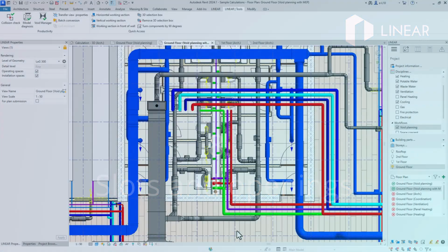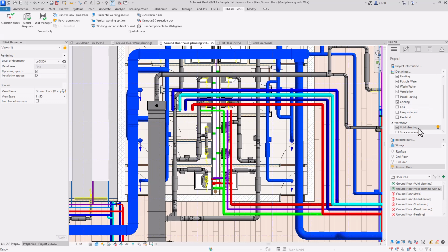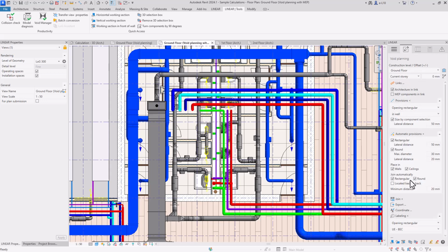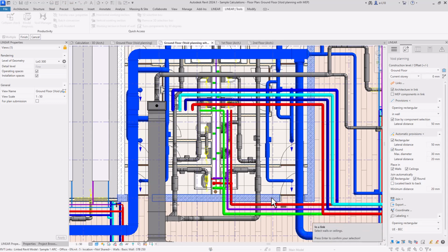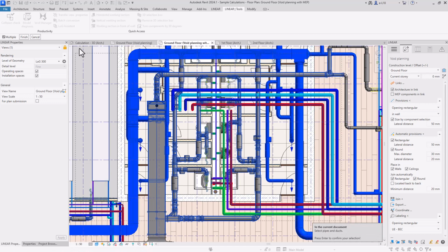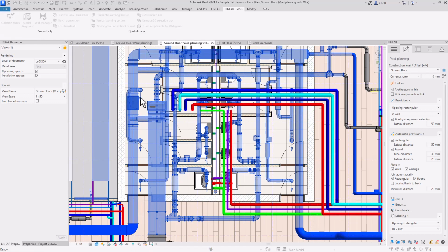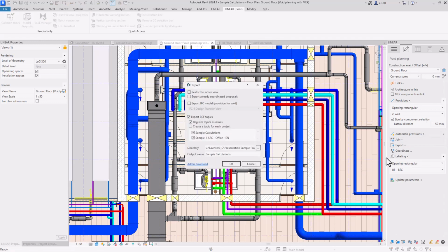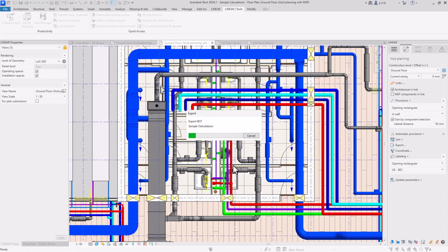As soon as the detailed and correctly dimensioned pipe network or air duct system is ready, reliable information on slots and openings in masonry and ceilings can be provided. You will find everything you need for this in the cross-discipline workflow, slot and opening planning. Whether manual or automatic, the program correctly determines the necessary opening sizes and positions and also provides you with all the information in BCF format for collaboration, optionally with IFC export of the openings.